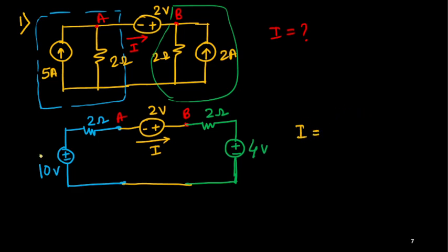So here this 10 volt, 2 volt and 4 volt, we need to combine. You can see how they are connected in this loop. So this is minus plus, this is again minus plus, the same direction. If I move in this direction, they are going to add. So this is 10 plus 2, because it is the same side, but this one is plus minus. If you come to this side, it will oppose, so minus 4.